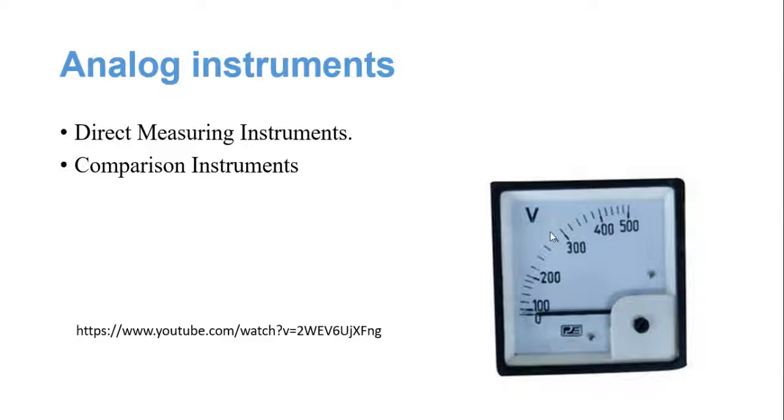By taking suitable precautions, if we need to measure the 230 volt input supply voltage of a single phase system, we need to insert the two terminals of the voltmeter by keeping the main switch off. After making a suitable connection, you may check that the connection is not loose, then turn on the switch, the pointer will deflect and you will get the measured quantity.